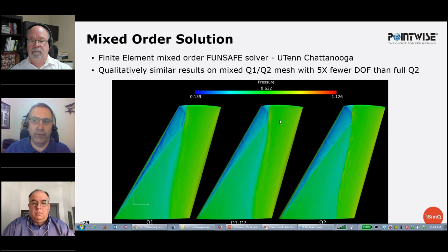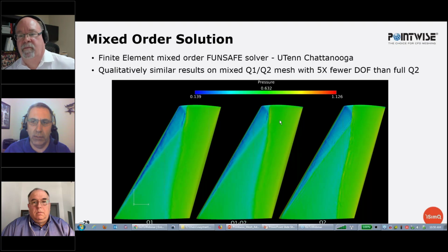So I'll take a first stab at this. Firstly, you are correct. We are adding another nonlinearity into the system here. We're changing the mesh as the solution is converging, and I mean the solution on the fine mesh, the ultimate solution, is converging. So it's important that you start with a baseline mesh which has certain best practice qualities. You want something that the models are supporting. You don't want to go so coarse that the model is invalid on that mesh. You want to resolve your geometry initially, because that's informing your flow field.